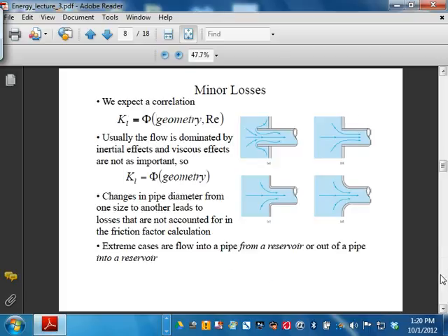Okay, so other minor losses. You already did a little bit of that in the flow measurement prac. Those two flow devices, the Venturi tube and the orifice plate, had losses there. That's why the ideal flow rate and the actual flow rate are not the same, because there are losses. And that CQ that you calculated is actually a function of the losses. So that's one example. A fixture, like a flow measurement device, will generate some minor losses.